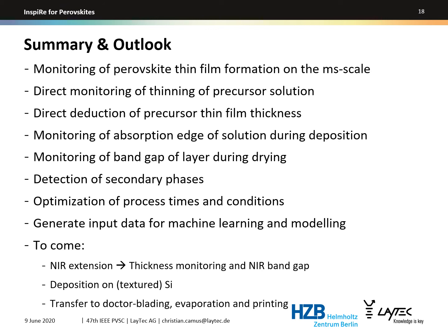You can monitor the absorption edge of the solution during deposition, as well as the bandgap of the layer during drying, and you can detect secondary phases and optimize your process times and conditions. And by that, you can generate input data for machine learning and modeling. In the future, we would also like to have a look at near infrared and at deposition on top of silicon or by means of other deposition techniques.